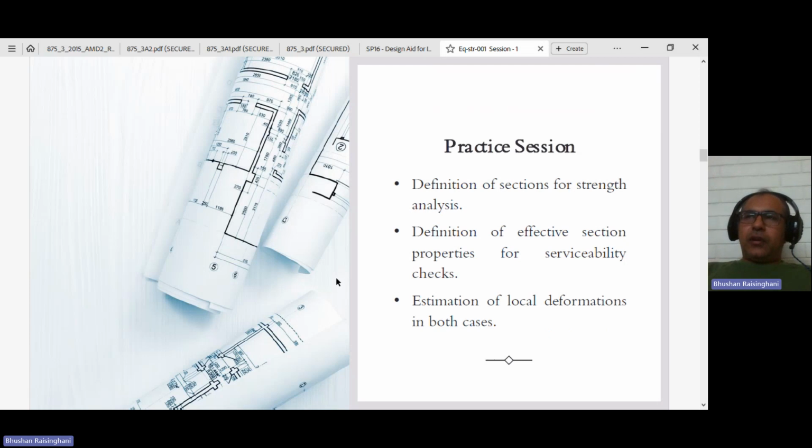Now in wind, if your structure is not going into the non-linear range, and if you are giving the cracked section properties in the wind case, in analysis, then your displacement will be higher for wind. However, once you design for it, your ultimate action is going to crack the structure. So basically, cracked section properties will help you to capture the higher displacement as well as the cracks during the ultimate load cases. So that is the basic agenda, so that you capture the exact reinforcement requirement as well as the time period of the building, using the section modifiers for the ultimate load case as well as the serviceability load cases.